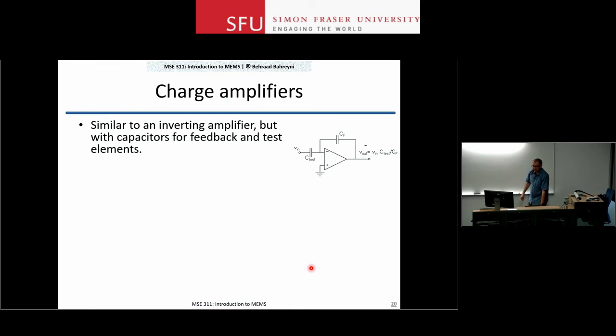How do charge amplifiers work? So here is an example. Notice that the input current to your op-amp is 0. So what happens? Well, you can approach this in two ways. If you want to go the impedance way and say the gain of this amplifier is ZF, the impedance of the feedback loop, over the input impedance Z1, with a negative sign, you can do that, and then you get this expression.